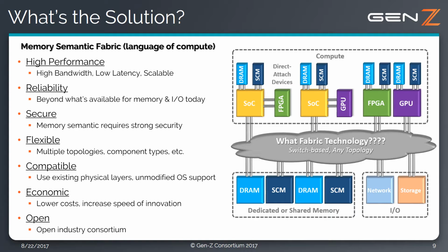It needs to allow SoCs and CPUs, memory, and I/O devices of multiple generations and types to be connected seamlessly together. It needs to support direct attachment of SoCs to memory and I/O, as well as enable a fabric where multiple SoCs can provision and share memory, accelerators, and I/O devices dynamically through the entire lifecycle of the workloads being hosted on this infrastructure.